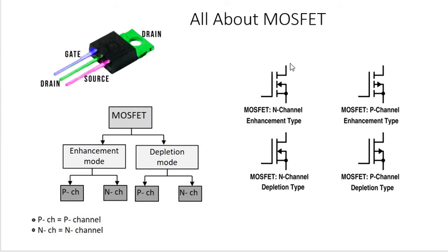We know that we can calculate the power loss by the formula I squared R. So if we know the amount of current flowing through this, and RDS(on), that is the drain to source resistance, which we can get from the data sheet, then simply by calculating I squared R we will get the losses. So in case of n-channel, these losses will be less compared to that of a p-channel MOSFET of the same capacity. Now let's move to the construction of MOSFET.